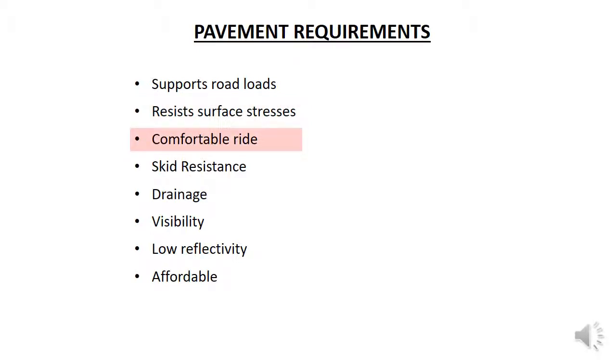The pavement needs to provide a comfortable ride, which means that the road surface is even without depressions or humps. Once again, it needs to be able to maintain this even surface for long periods of time without maintenance. Once depressions and humps start to form, then vehicles bouncing on the road create additional impact loads that accelerate the pavement deterioration and eventual failure.